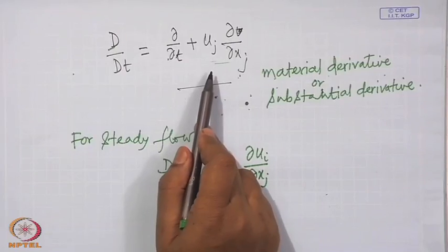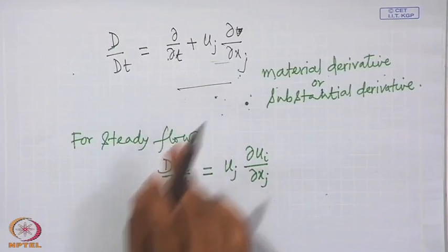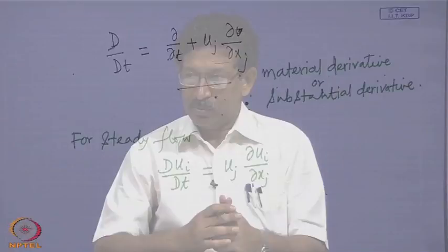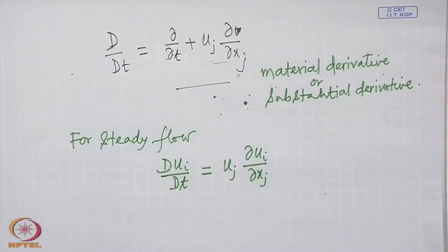And the second part is the change in velocity due to the change in particle position from one spatial point to another spatial position. So, this is due to a real transfer of material from one position to another, and is called convective acceleration. In general, these are called local change and convective change.